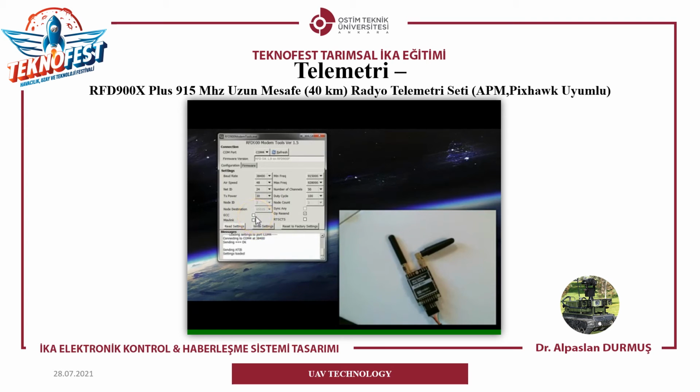This error correction, the RFD 900 Plus changed something going from the 900 to the 900 Plus, where they limit the packet size and change the way the serial buffer works. And this messes with our error correction. We have our own error correction, so we do not need this checked. Our error correction takes care of all of that on the Pi and the ground station side. Op resend, leave this selected. Ready to send, continue to send is not being used. Leave that unselected.